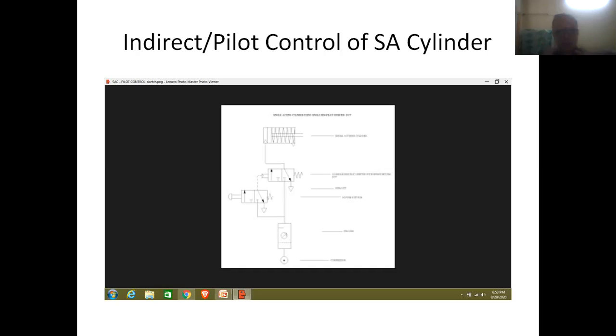And this is called the return stroke of the piston. So friends, this is the circuit operation. It is divided into two phases. In the first phase of operation, the pilot valve will be coming to first position and it will be placing the DC valve in first position. That is used for performing the forward stroke of the piston.